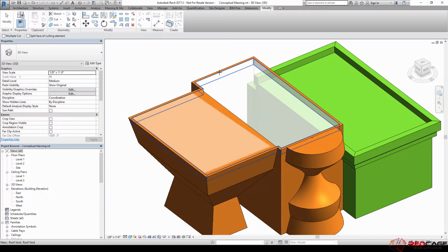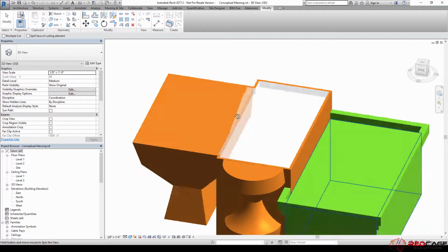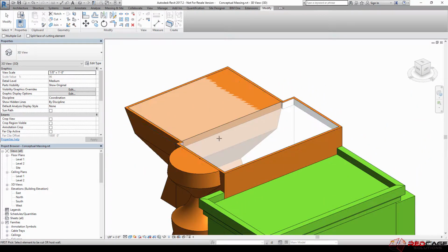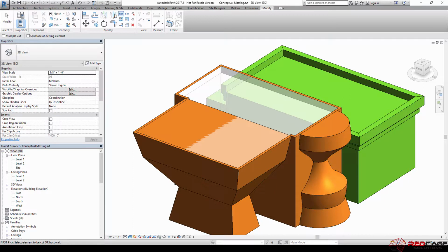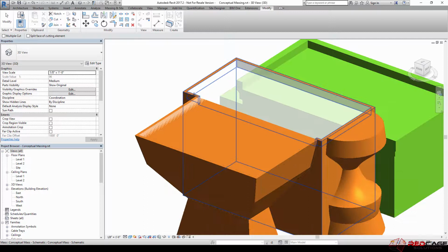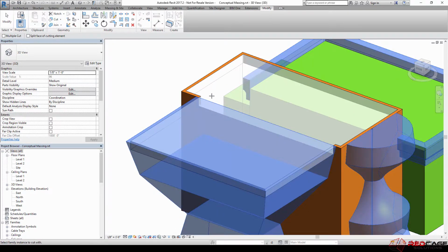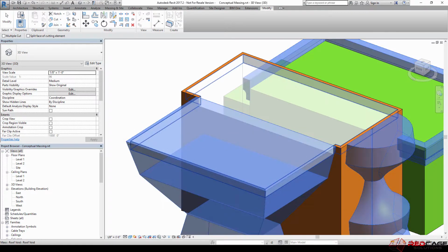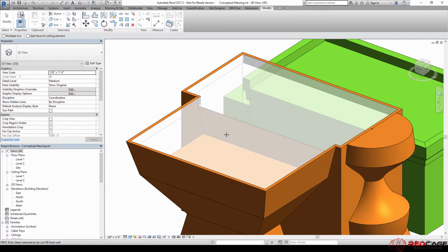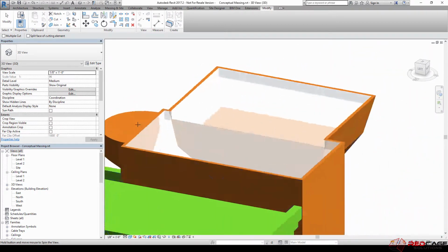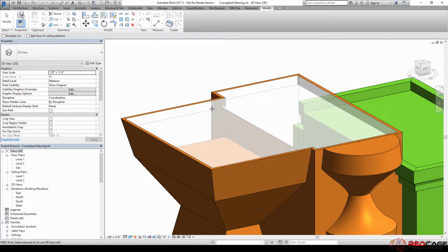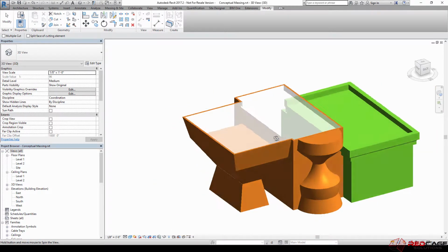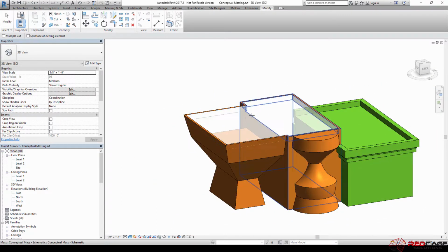Now you can see there's this white spot inside where we've removed that geometry, but it's only happened on this one individual form. Notice that I'm carrying out this command in the project environment, not within the massing itself. I'll do that again with my in-place mass, and we should see that come out. So cut, I'm going to grab the outside one and then this one, and now you can see it's removed that geometry from our in-place mass as well. I'm not overly concerned about what's going to happen inside. I just wanted to remove that geometry for the time being to show you how that behaves.